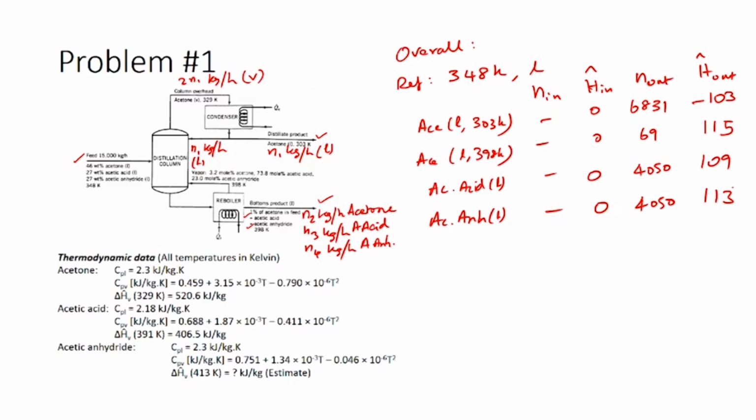So, now we can calculate the total change in enthalpy using this, and we would have to plug it into the general energy balance, the overall energy balance equation, to get Q_R. Assuming that there is no energy being used in the distillation column, we will only account for Q_R and Q_C, because those are the only terms given to us where heat is being supplied. So, using that assumption, we will calculate Q dot as Q_C dot plus Q_R dot, and fitting it back into the general energy balance equation, this would be equal to delta H dot.